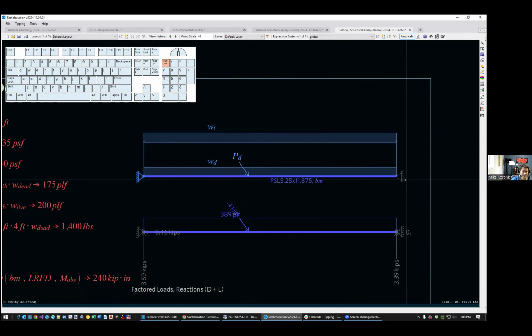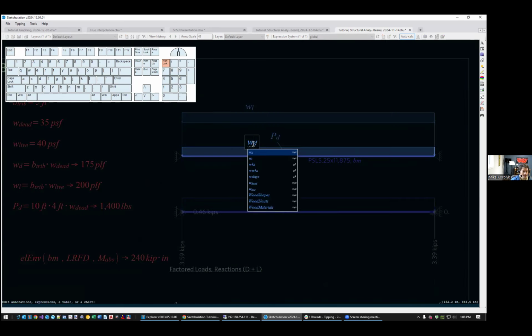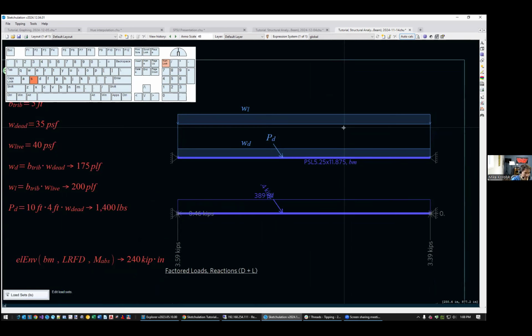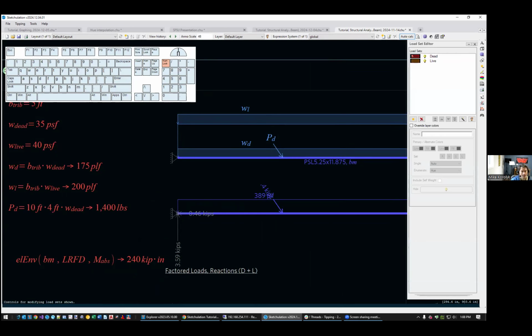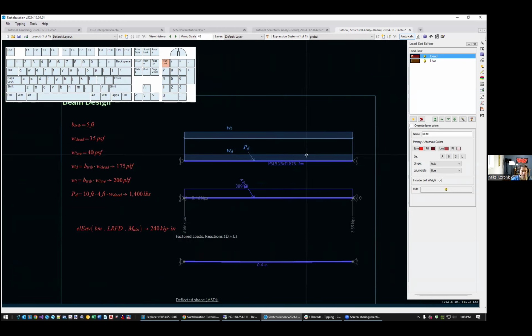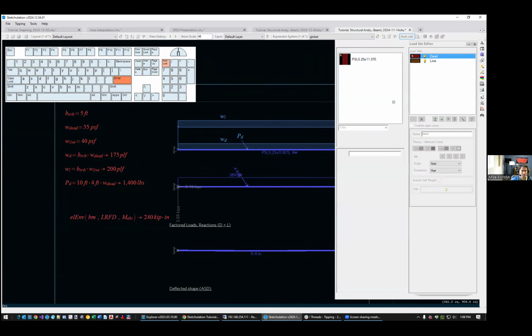And our restraints, command R for the restraints. Linear loads, LDL. We put those in there, and then we edited them to put in the expressions for our loading. We created load sets, command LS, and we can see what load set they're on by overriding the layers. And we selected one, and we put the paintbrush and applied it to the dead load and the live load to create our model. And then we made our frame element type, FET.